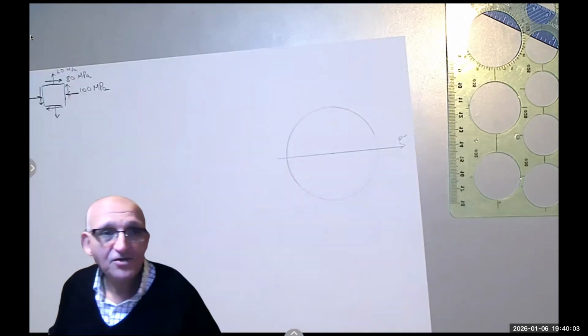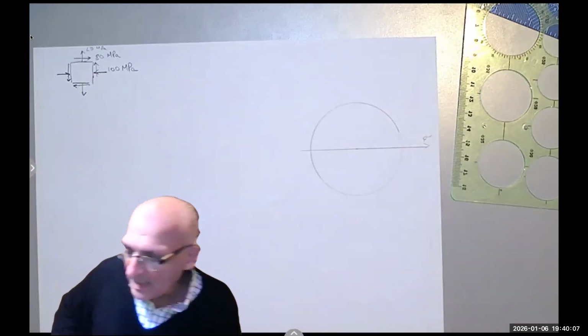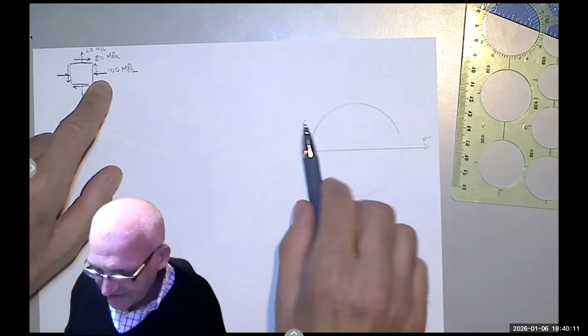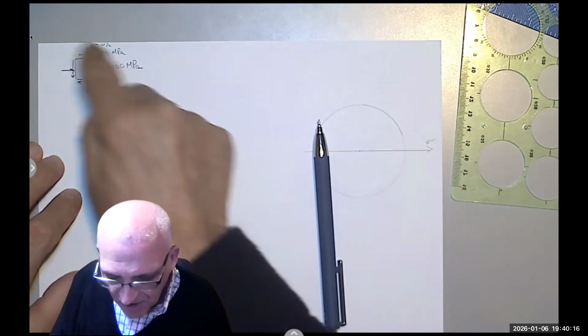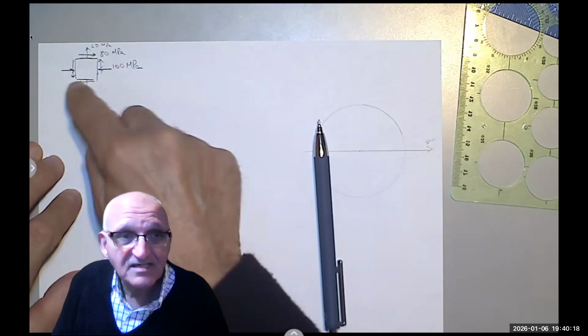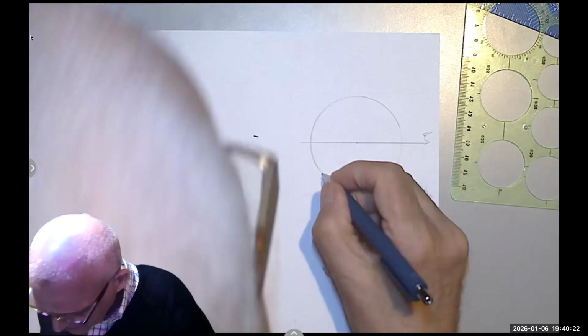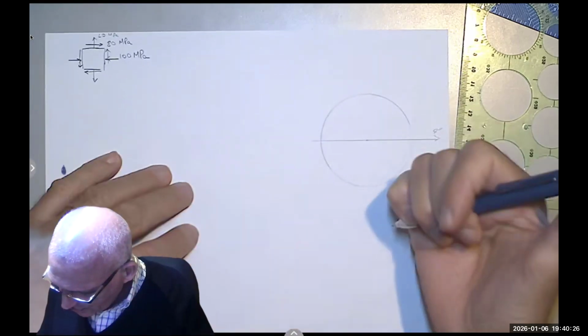Suppose this is the scenario. So how do I plot that here? Again, as I said, the x is compression, so the x is to the left, somewhere here. And the shear on it is counterclockwise, meaning positive. Positive is down, remember. So I will have a point somewhere here to the left and down. Where exactly, I don't know, and I don't care.